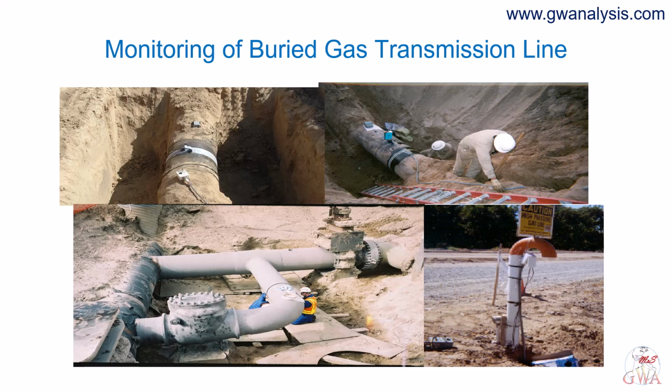For the reasons we discussed on the previous slide, attenuation in the buried line is high. So a single inspection has a short range and high threshold, but the comparison between this year and last year is not limited in the same way, because the coherent noise from the soil and the corrosion repeats. What changes is the defect.